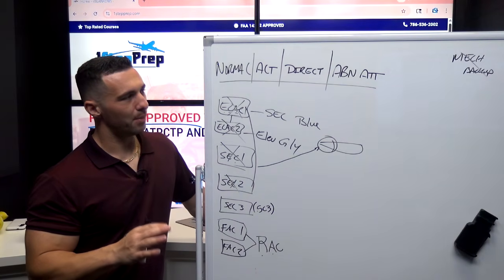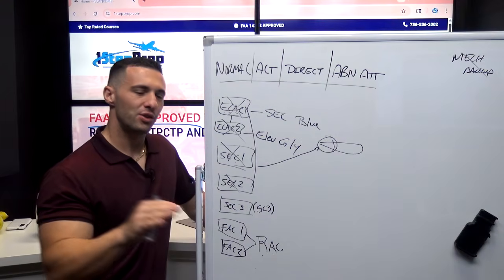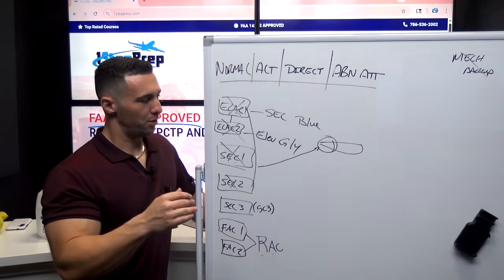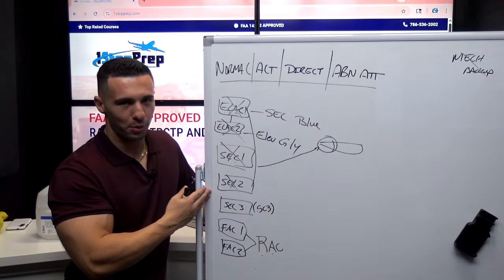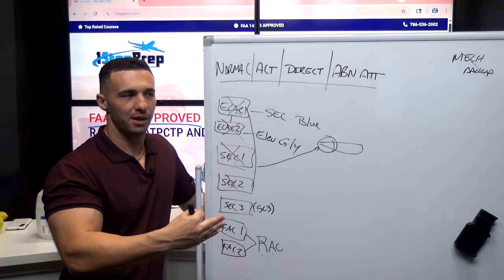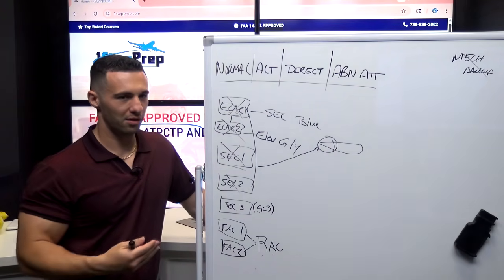But mechanical backup, I just want you to know, is the absence of all laws. It's entered into when we lose pitch control to the elevator, which would translate into basically loss of one of these 4 computers. There's 3 ways to control the airplane in mechanical backup, with the objective not to be to land the jet necessarily like that, but just to reestablish one of these laws.